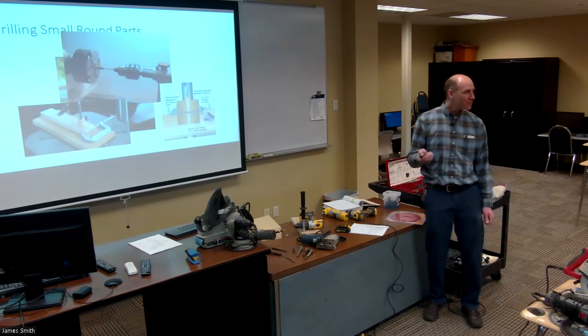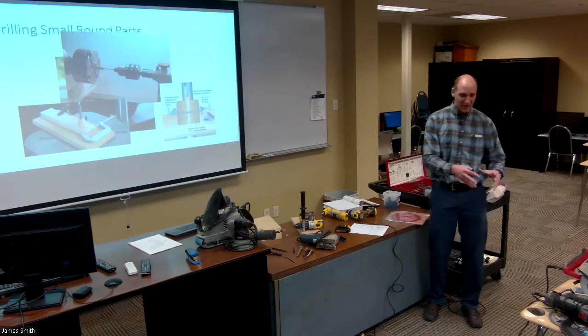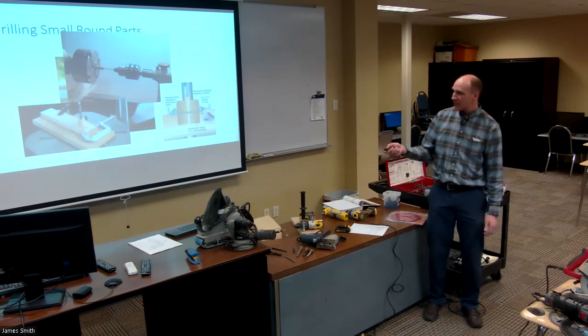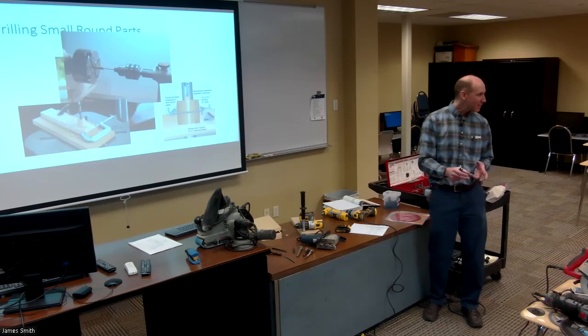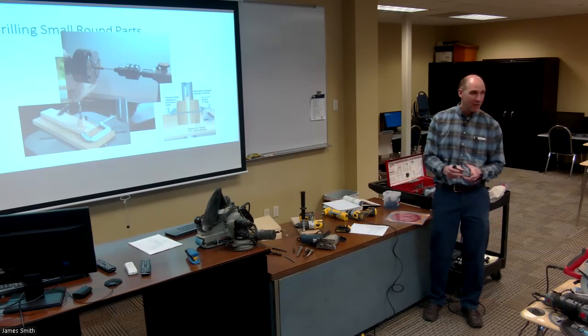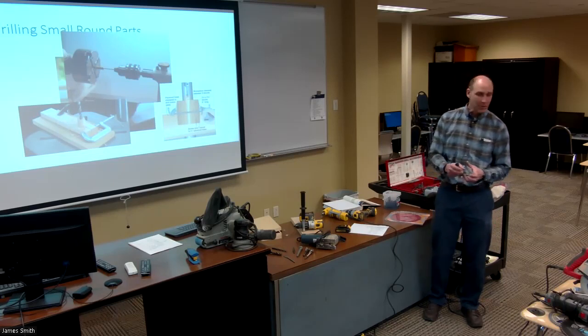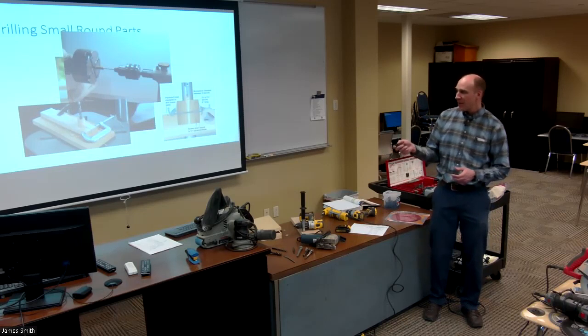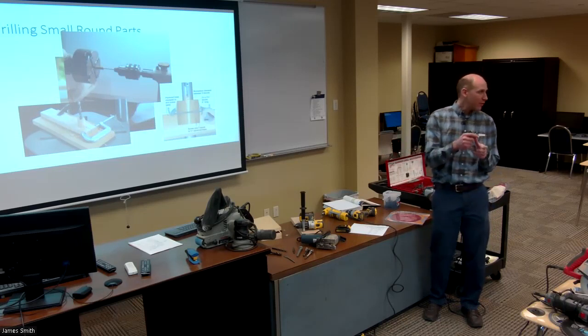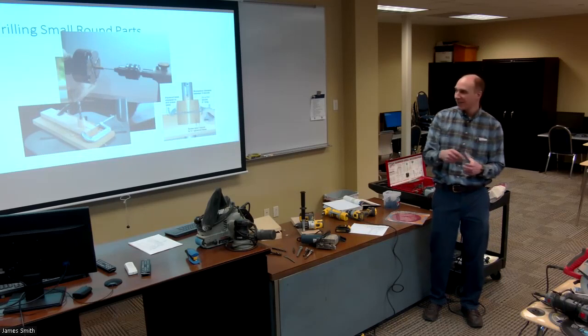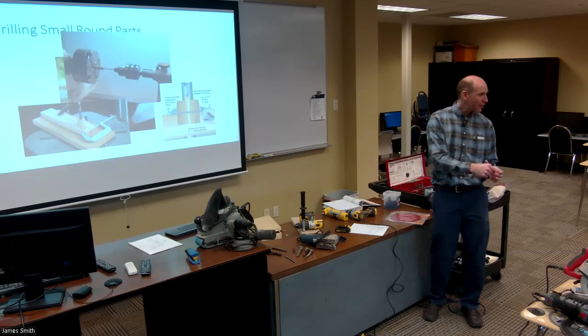If you're going to use a drill press, you almost have to get your board set up. Basically, take your board and cut a kerf in it, because that's the only way you can clamp onto that round object and keep it from spinning as you're drilling it. Then load up in the drill your 1-inch bit and drill the hole that would be the outer diameter, then insert your part in there.